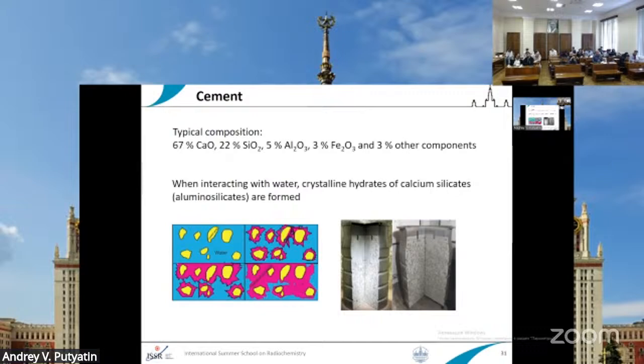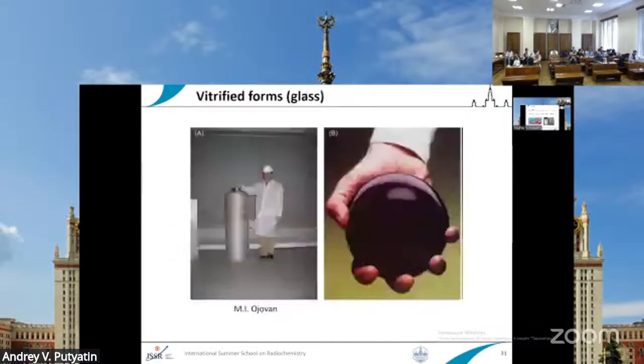Actually, we, and some other groups, did research on the stability of cement matrix, and the mechanical strength and the leaching of radionuclides from cement are more or less the same even after the high doses of radiation typical for high-level waste. But the only concern from the regulators is the formation of gas from the water due to radiolysis. We cannot avoid the formation of hydrogen from the cements. That's why, at least at the moment, cements cannot be used for high-level waste.